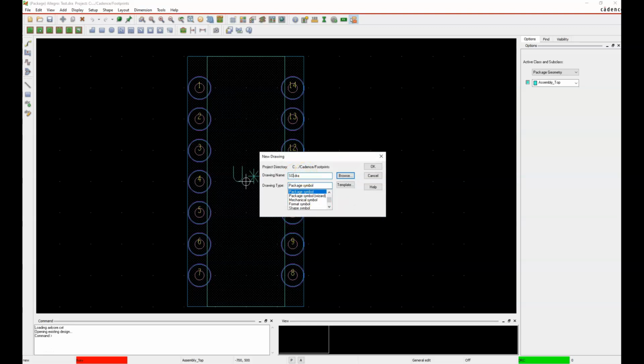And so the naming convention says this should be SOIC 127P, and then it was 6 by 1.75, and it was 6.0. So I really should do 600 because that's 6 millimeters, so it's 6.00. Otherwise, 6 might be interpreted as 0.06. So it's important to put the 600 that I almost left off, and then dash 8 pins.